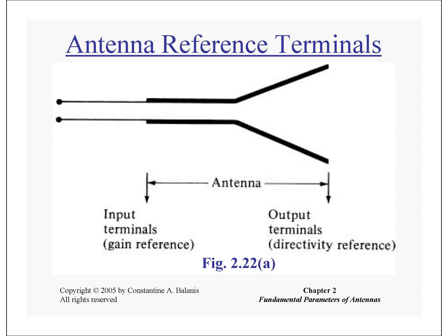So the directivity is completely dependent on the radiation pattern. However, if you see the gain reference terminal, at the input terminals, the gain is dependent not only on the pattern, that is directivity, but also on the reflection and the structure losses. So two terms will be considered while calculating the gain, that is the reflection here at the end, and also the losses.